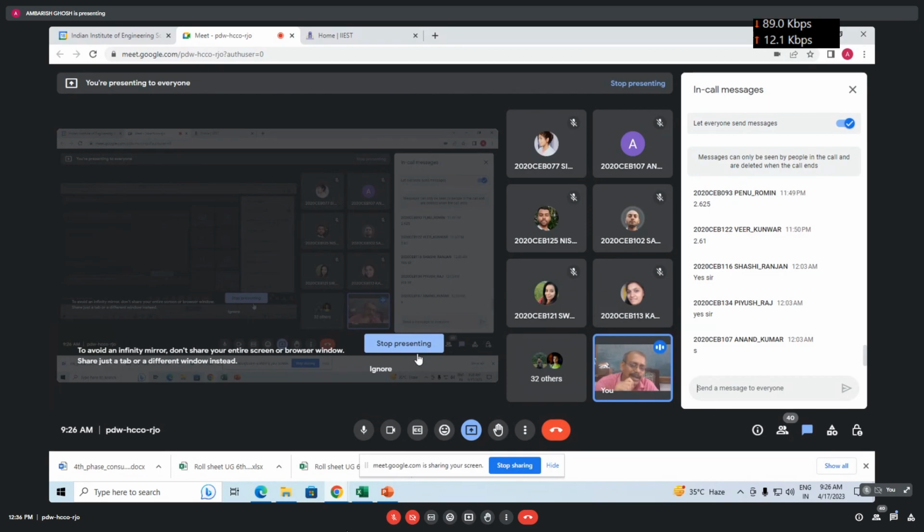Once the load is known, then as per your soil profile, you can change the diameter and get the pile diameter to take the allowable load that is required from the structural loading point of view. Accordingly, the diameter will be fixed. So you will do the calculation for 500, 600 or 700, then see which diameter is comfortable to take your load, and that diameter will be fixed. Length also is the same thing. Length, you will always try to rest the pile in a stiffer layer, and depending on the length you will also calculate the capacity.